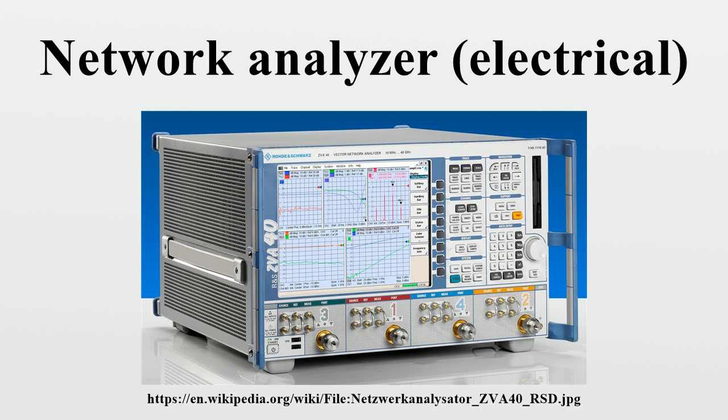S-parameter measurement with vector network analyzer. A VNA is a test system that enables the RF performance of radio frequency and microwave devices to be characterized in terms of network scattering parameters, or S-parameters. The diagram shows the essential parts of a typical two-port vector network analyzer. The two ports of the device under test are denoted port 1 and port 2.